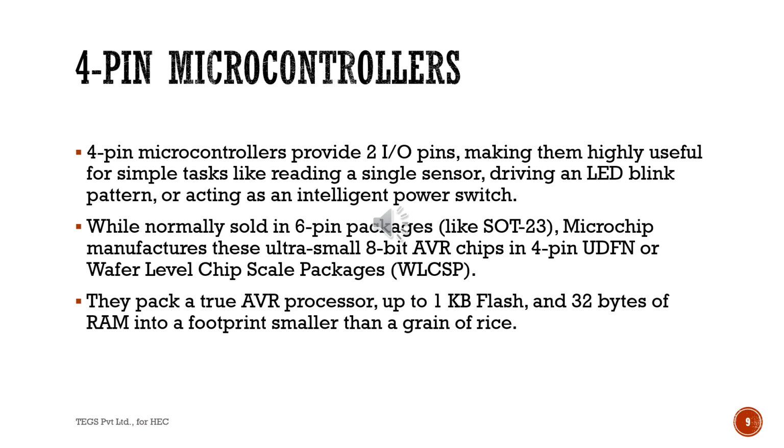While normally sold in 6-pin packages, Microchip manufactures these ultra-small 8-bit AVR chips in 4-pin UDFN or wafer-level chip scale package. They pack a true AVR processor with up to 1 kilobyte flash and 32 bytes of RAM into a footprint smaller than a grain of rice.